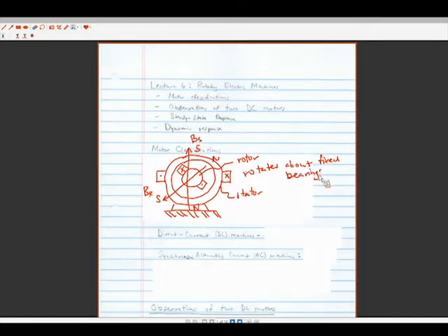All right. And you'll see that when we pass these motors around. All right, so if we look at what we have here, it doesn't really matter if these are north or south, but we know that the opposites attract each other, right? So if we look at this, the rotor is going to have an applied torque on it in this direction to align the south and the north magnetic fields, right? So this torque is going to be in the counterclockwise direction for this configuration.